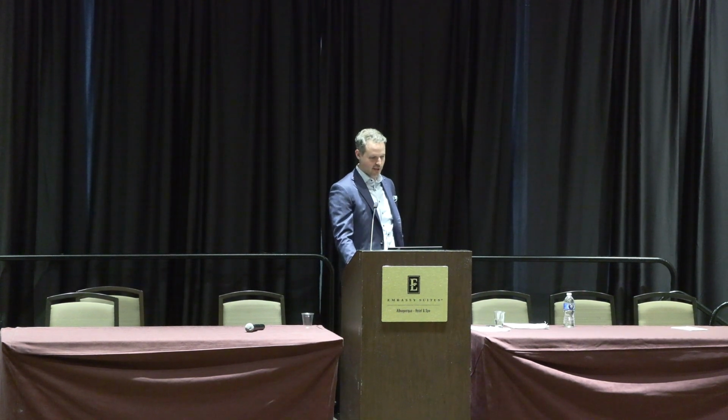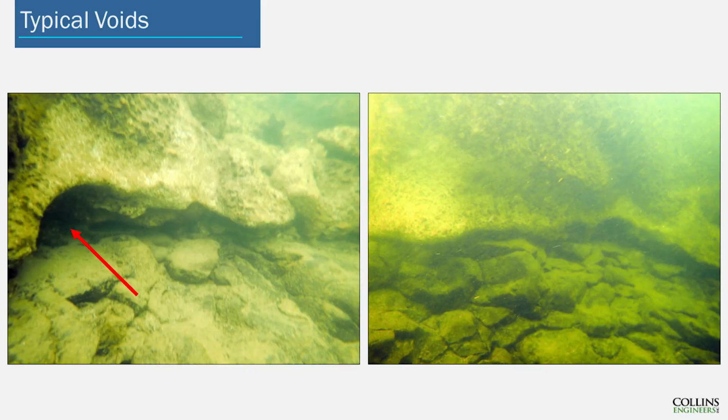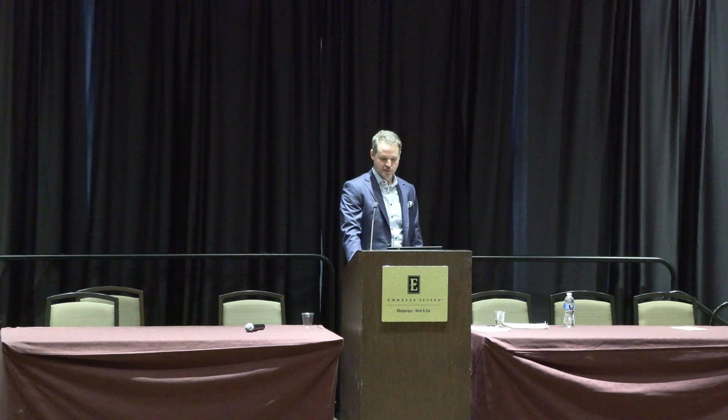So here's what it really looks like for comparison. These are pictures of the voids in the encasement located at the interface with the channel bottom. The channel bottom is smooth bedrock for the most part, and the concrete has been worn smooth from years of water erosion. It almost looks like rock. Details this small can be hard to discern from sonar data, even with something like a multi-beam, especially when you have a rocky bottom that causes so many acoustic shadows, but something like this would be immediately obvious to a diver. But since we have this image for comparison, it helps make more sense of the sonar data.